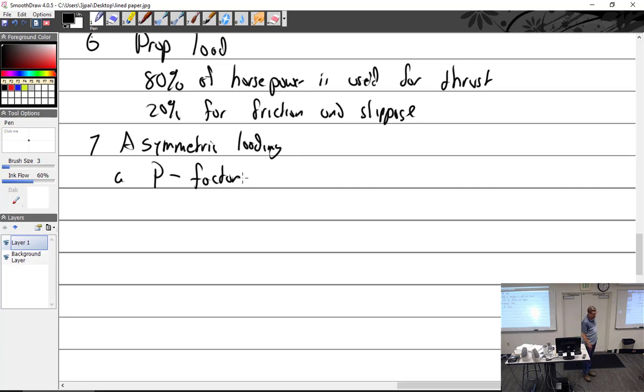Well, now I'm glad I brought this in here. Right now, this is sitting level. And if we were to measure this blade angle at what station? 75%. About right in here. You see that? About yay much. If I look over here, it's about the same dang thing. Not only about, it's exactly the same.